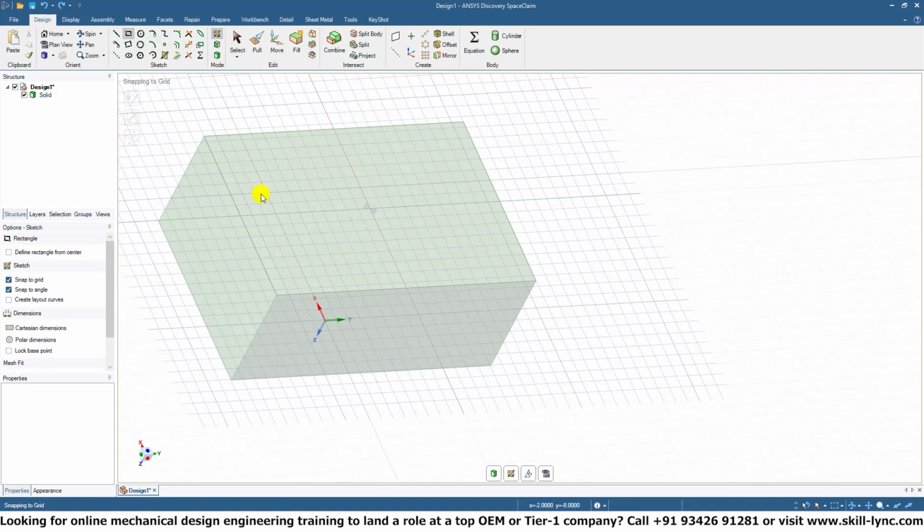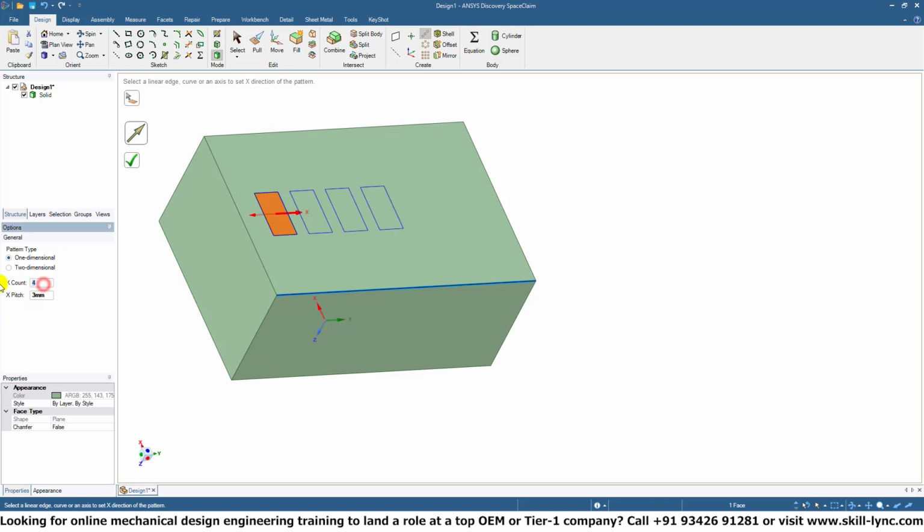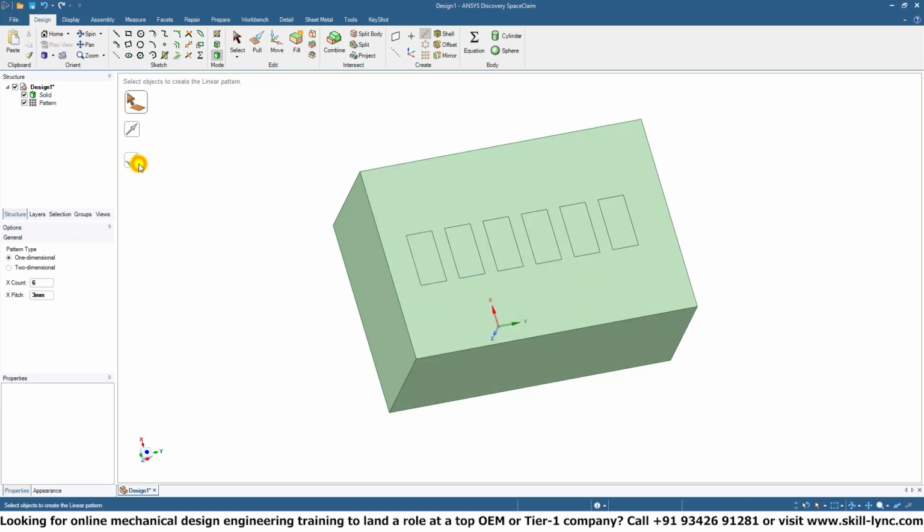Let's create another piece of geometry over here for us to replicate along, let's say, this edge, this dimension. Let's do the pitch. Let's say 3 mil. We can go with 3 mil. Let's see how that works out for us. Doesn't like 7, maybe 6. 6, there we go. Just along the surface. Okay, should be good.